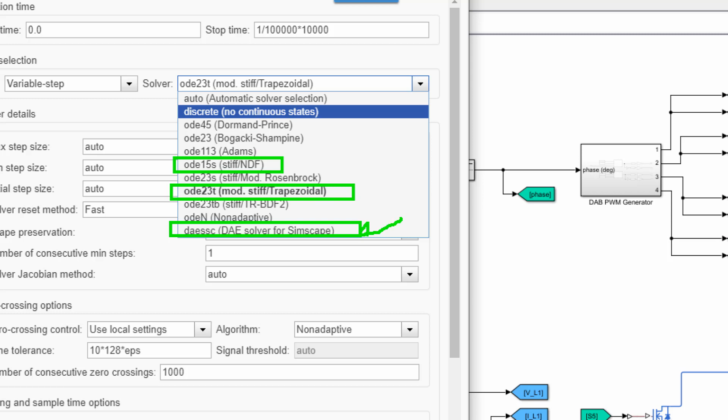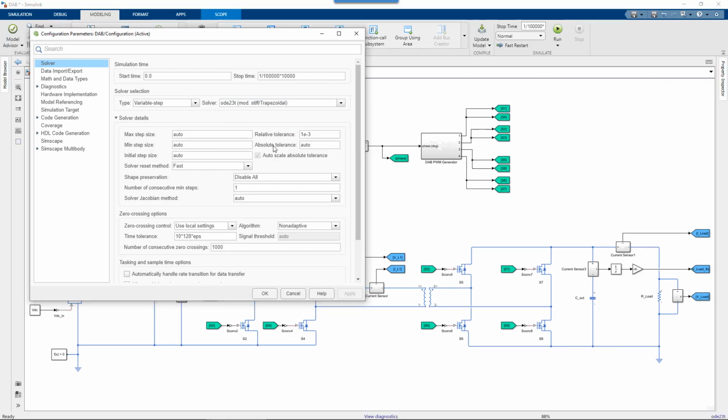This is the most robust, most powerful Simscape solver, so it's also going to be the slowest. This is the most generic, or most generic for a simple one. And this one is best optimized for electrical systems. Why is that? Well, all of these solvers use numerical approaches to solving their equations. They're not analytically solving everything. They're taking time steps and estimating solutions to equations. You don't need to know what's going on with that.